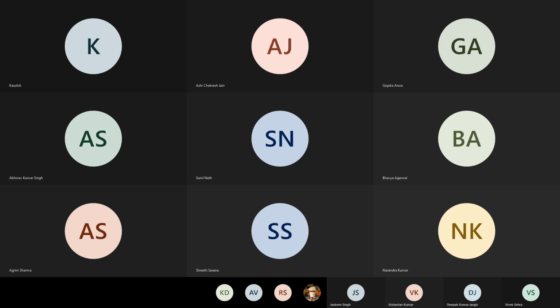And the units here are calories, so you have to convert them to joules. So it's calories per gram mole per degree centigrade or per Kelvin. That's these values. If you just take these values and multiply by the difference in temperature, 533 minus 298, that will be the enthalpy change, the sensible heat change for that particular reactant or product.